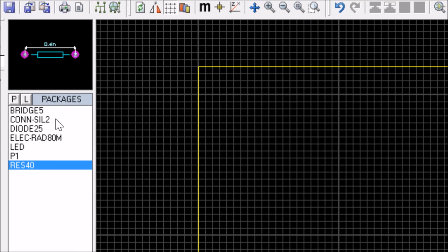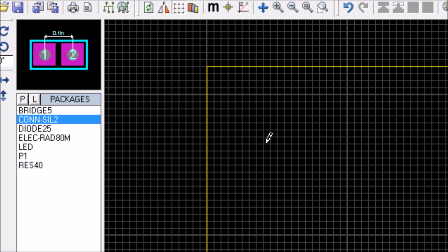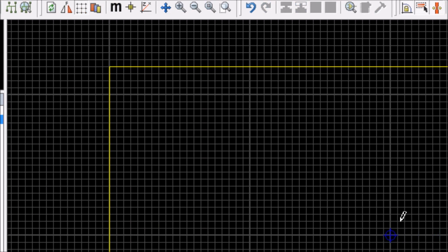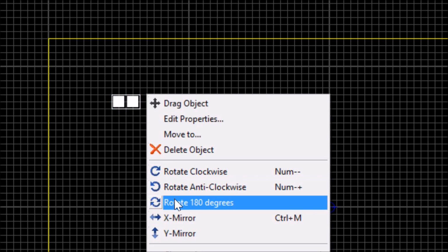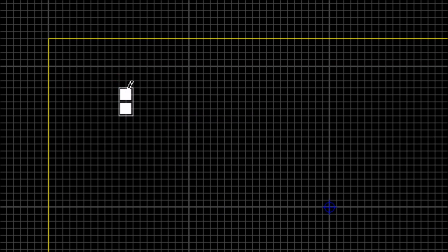So first of all, I have a transformer, and I told you guys I'm using these two pins for the transformer inputs, and my transformer output can be hanging to external circuitry. I told you guys I'm not putting my high voltage on the PCB board because it's a low voltage board. So go ahead and drop this guy here, and if you've done that, let's rotate this guy. Right click and rotate. All right, so this is my first input. I hope this is making sense. So whenever I get my transformer, I connect my transformer directly here.